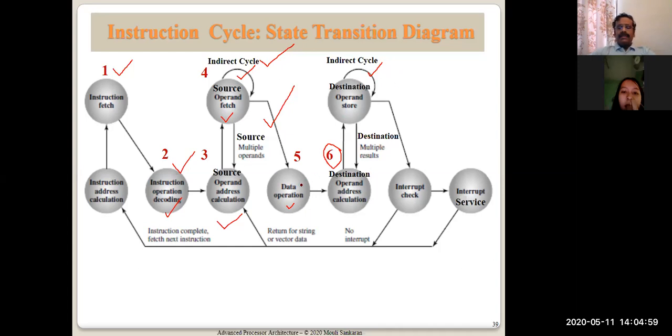In the ARM example, it is not possible. In a RISC system, you know that load and store are different instructions, and all other arithmetic logic operations always perform their jobs taking the operands from the registers. So in the RISC architecture, we do not have memory cycles for writing the result back, because there is a separate instruction doing it, which is the store instruction.